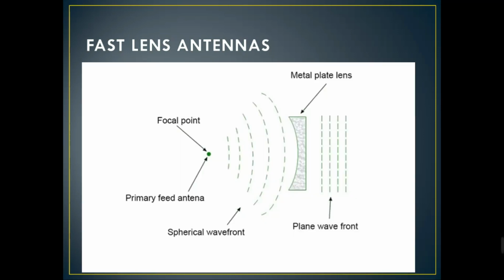It occurs because the phase velocity of radio waves in waveguides can be greater than the speed of light. Since the thicker parts of the lens decrease path length, a concave lens is a converging lens, which focuses radio waves, and a convex lens is a diverging lens, the opposite of ordinary optical lenses.